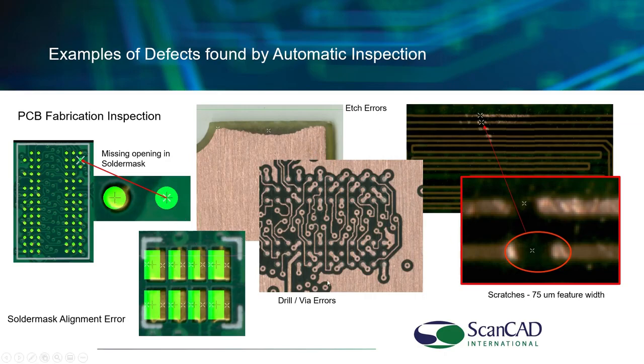We also can inspect holes. These can be punched, drilled, laser cut, etc. in any kind of material, and we can inspect those holes. We have the lighting, transmissive lighting that push light down through the holes if you wish, etc. Here we have an etch error and a chemical etch process. And finally, on the right-hand side, we have some scratches on a part here, and so we can check for surface defects, scratches, those kinds of things.